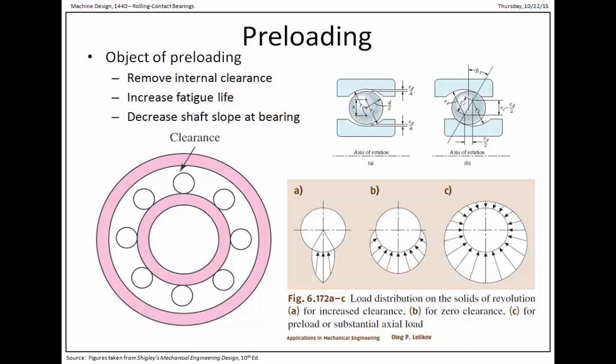So that'll be something we're going to look at. One of the things I want to discuss just quickly is preloading. I mentioned the Belleville springs on the end caps, which tend to put a force and shift and give a positive force between the bearing, even when there's no load being applied. It's already preloaded. That is a way to increase the fatigue life.